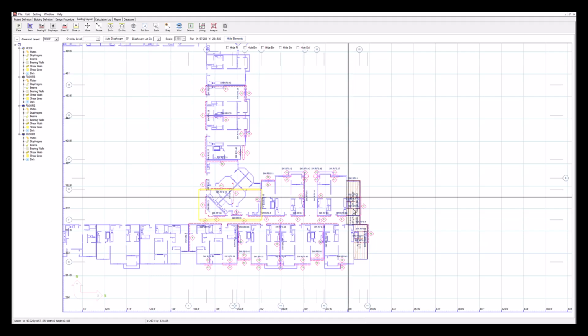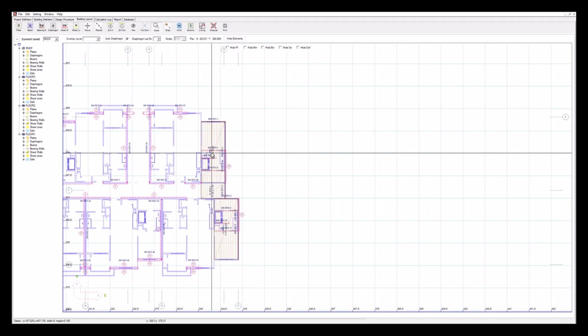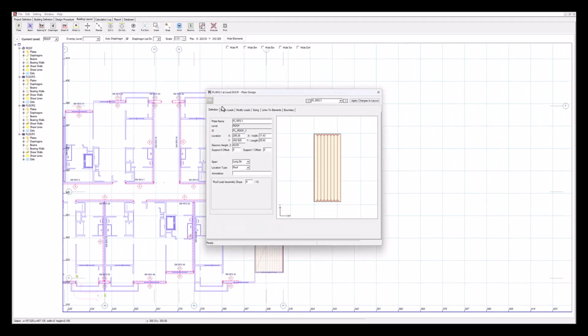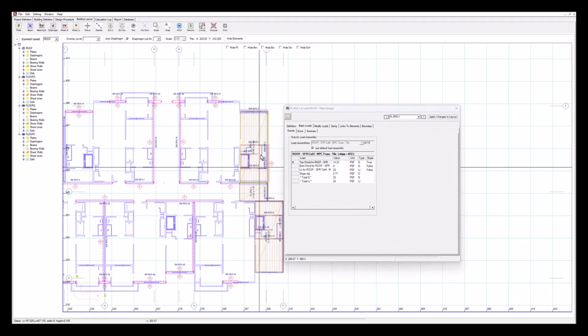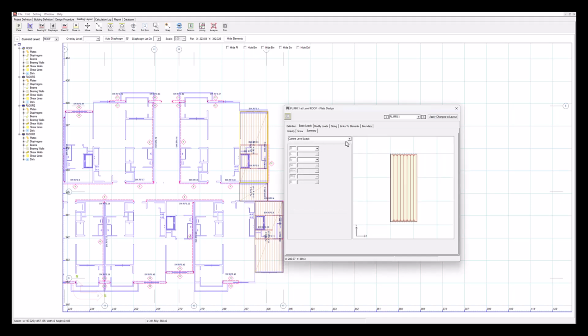So my plates here, if we zoom in, you'll see that this is going to do the gravity loads for us. So the plate definition here, if I click on that, it gives us information on how the plates are defined. The loads are also determined directly, and this is for your gravity loading. So you'll get your gravity loading on that plate in the vertical direction, and you'll have snow if applied, and then you'll see the total loads applied to this plate based on dead load, for example.